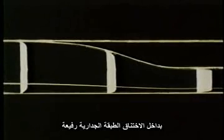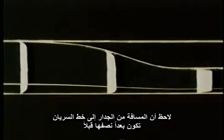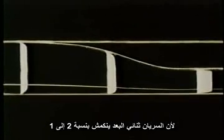After the contraction, the boundary layer is thinner. Note that the distance from the wall to the streamline downstream is about half what it is upstream, because the two-dimensional flow contracts 2-to-1.